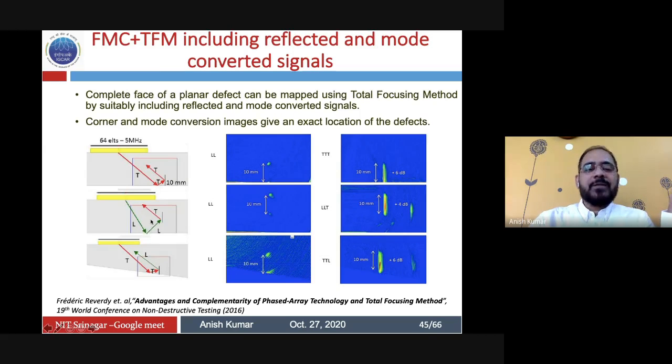But you will also have another transverse wave going here, which will follow sin I by sin R equal to V1 by V2, where V2, if you take the shear velocity, is about half. So with sin I by sin R equal to 1 by 2, at that you will have the transverse wave also coming, and that may go at a different angle. And all those are picked up by one or the other receiver here.